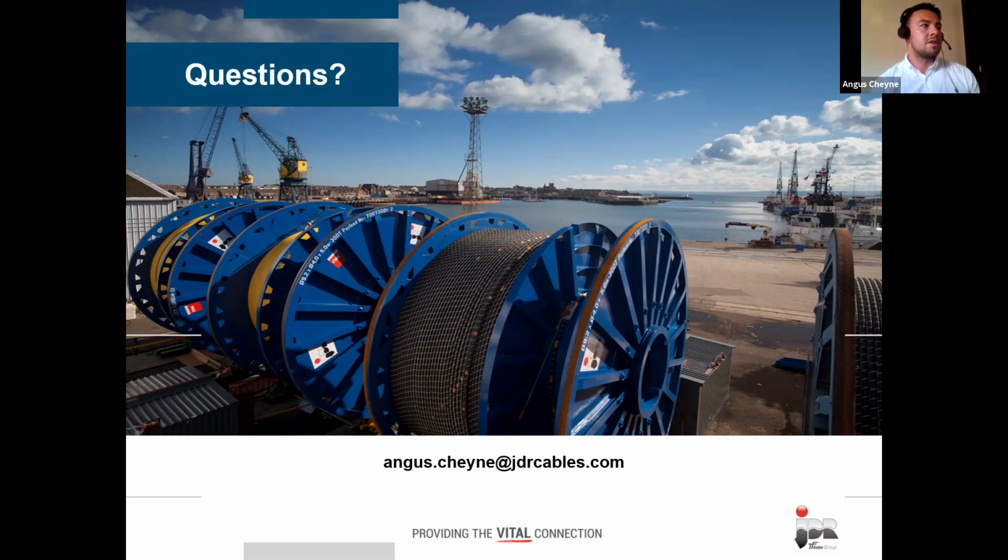Do you have a case study for cutting and retrieval of subsea cables? I'm not sure if we have a case study as such, but we will have experience of that, and it is something that is occasionally done in abandonment scenarios. Potentially, if there's poor weather, then you may have to cut the product, abandon it, and then retrieve it at a later date and return with the installation.